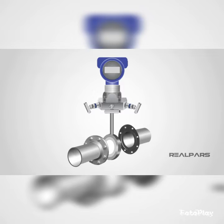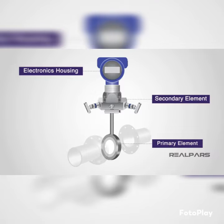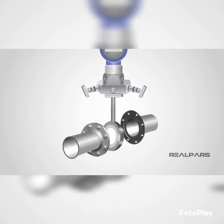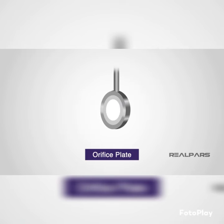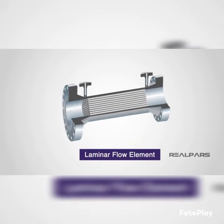A dP transmitter is a pressure measuring gauge, or an electrical device that uses 2 elements to measure the differences of pressure in a sealed container, such as a pipe. dP transmitters will have a primary element, a secondary element, and an electronics housing. The primary element will produce a difference in pressure as the flow in the pipe increases. Different types of primary elements include orifice plates, venturi tubes, pitot tubes, flow nozzles, laminar flow elements, and wedge elements.